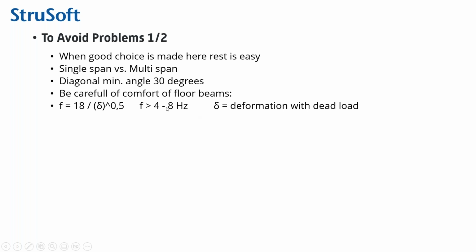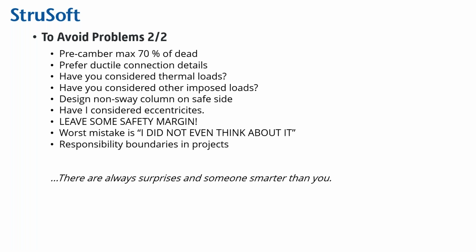And the comfort criterion like vibration is also important. So this is the rough hand calculation of the eigenfrequency of the floor. So make it so that even if above 10 hertz is a good selection here.